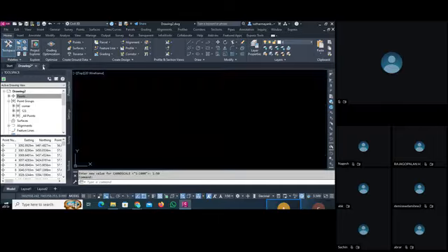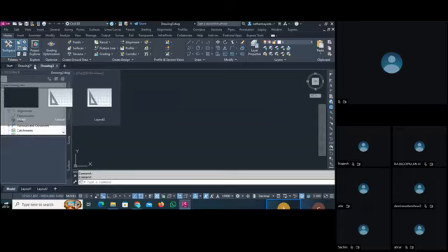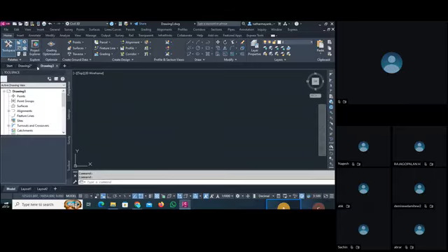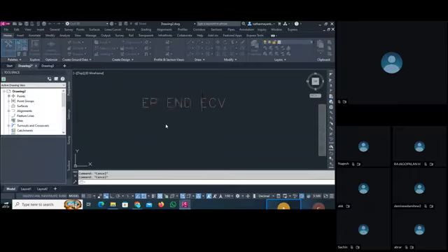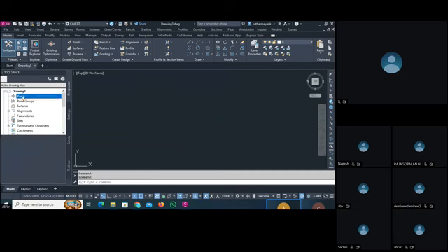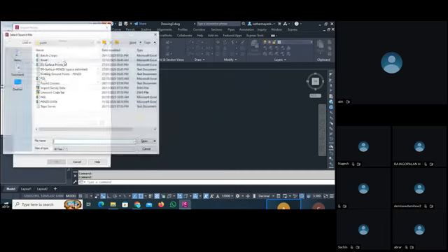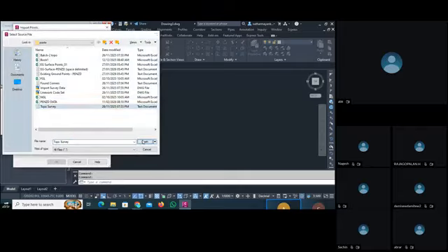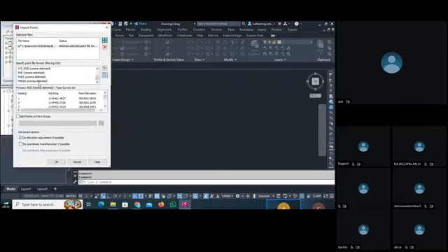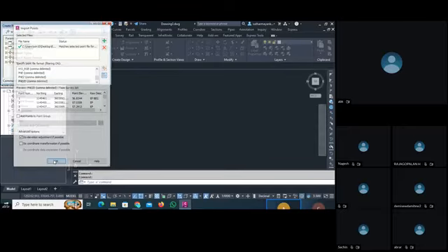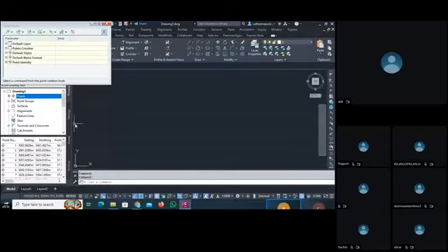Now the second thing, let's do this again. I will show you the surface now. Let's import points again. This time we are not creating a new group; we just import our points. Again I set our point file format, and this time I am not changing anything. I just open those points and show them with the help of Z enter, E enter.